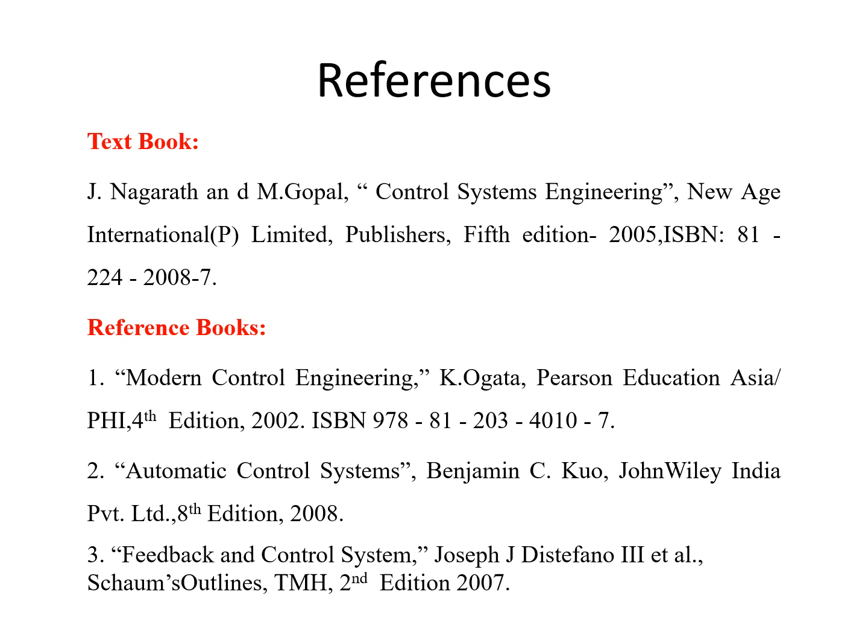The one important concept you need to remember in today's session is, if all the poles lie towards the left half plane of your S domain, then the system is said to be stable. If any one of the poles is lying towards the right half plane of your S domain, then the system is considered to be unstable. And if the poles lie on the imaginary axis, then the system is said to be marginally stable.